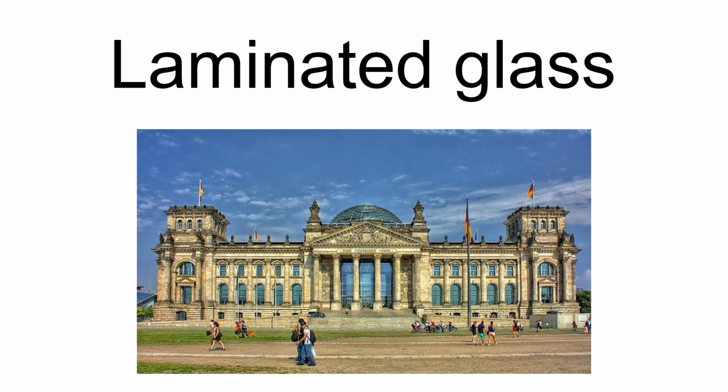It has a larger break pattern than tempered, but because it holds its shape, unlike the wet blanket effect of tempered laminated glass, it remains in the opening and can withstand more force for a longer period of time, making it much more difficult to get through. Laminated glass has similar properties to ballistic glass, but the two should not be confused. Both are made using a PVB interlayer, but they have drastically different tensile strength. Ballistic glass and laminated glass are both rated to different standards and have a different shatter pattern.